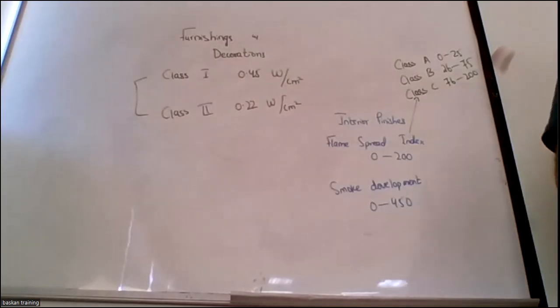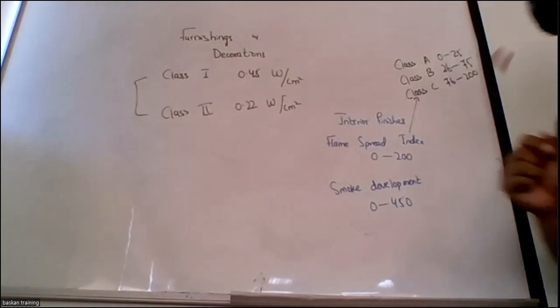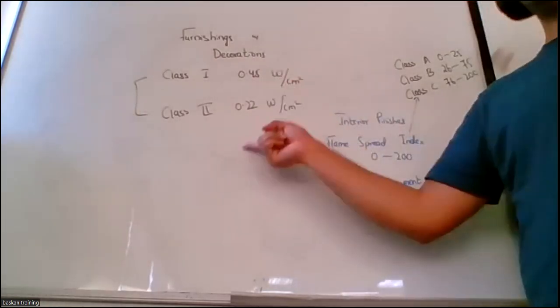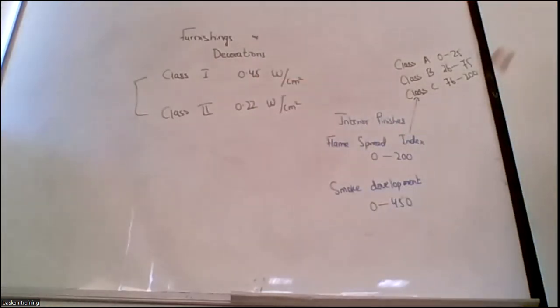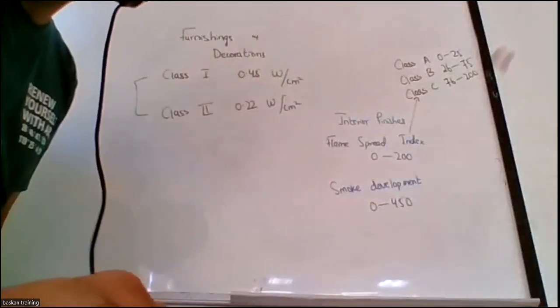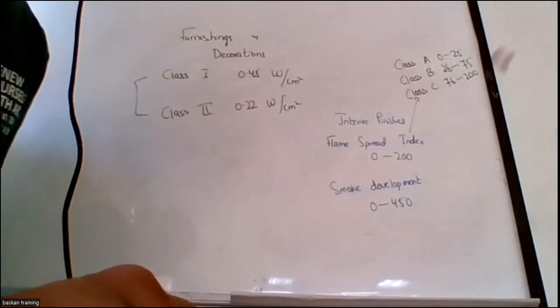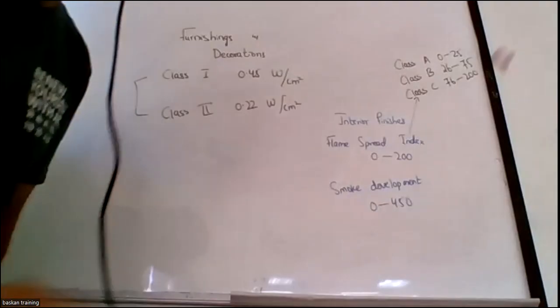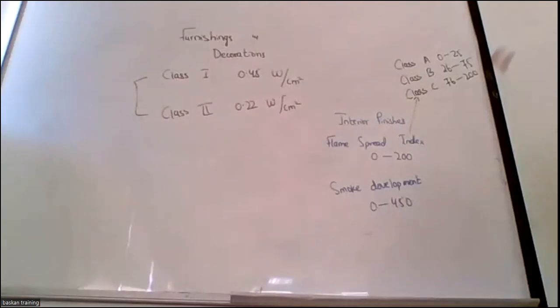in the examination they can give you a question, for example, for sprinklered buildings, the buildings that already have sprinkler protection, which classification will be used? Remember one thing, NFPA 101 focuses on both designs, new and existing buildings. So for sprinklered buildings, which classification will be there? Sprinklered buildings, class 1. Why?